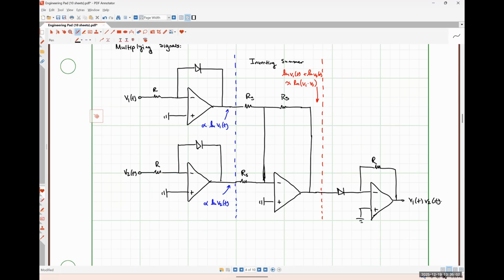So if you used an integrating amplifier like the one that we developed in class, it will automatically get rid of that negative sign. Whereas if you used a differentiating amplifier, you might have to pass it through just a non-inverting amplifier with a gain of 1 to flip that negative sign into positive or something like that.